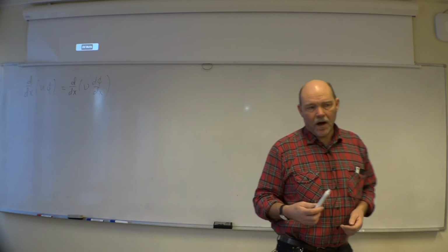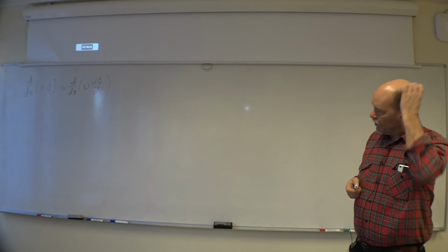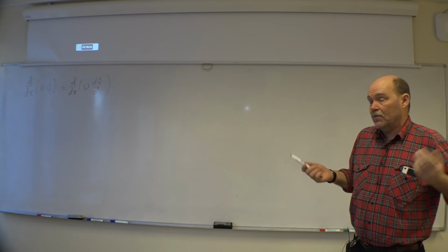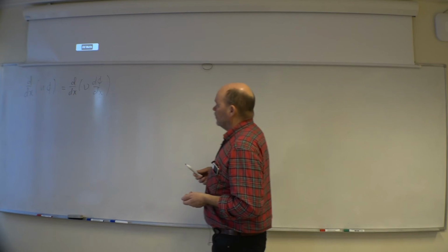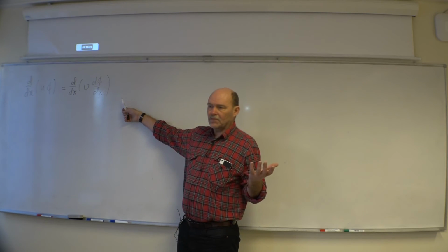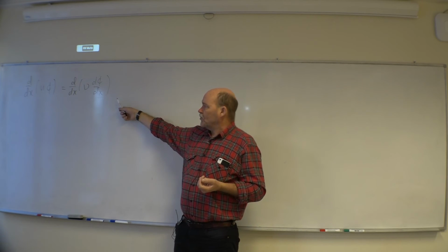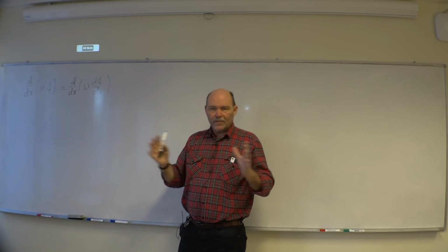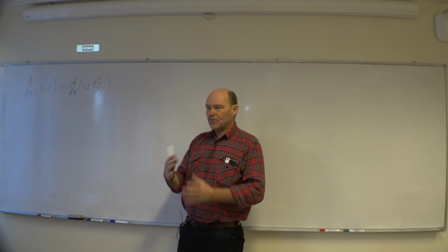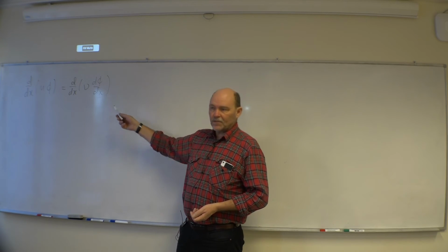The philosophy behind them is quite different, but the end result, the algebraic equation system, will be identical. Here, of course, with finite volume, that's the strength. You don't have to use a constant volume. You can have different delta x's, delta y's. You can have unstructured meshes. That's not so fun with finite difference.